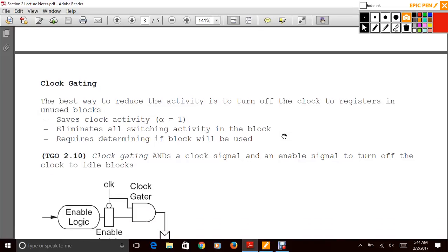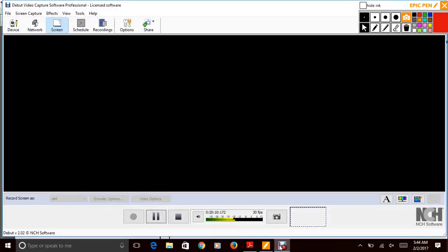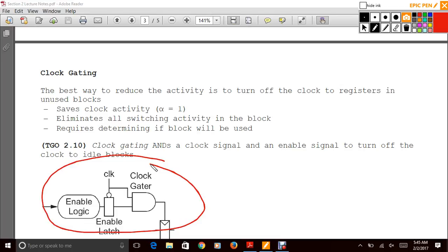So next, I want to go over some fundamental concepts on clock gating. How much time have we used? 20? Okay. Basically, there's a lot of ways to try to reduce power. The main idea is that we're going to focus on how to reduce power by turning certain portions of the circuit off or limiting the amount of power that's used, particularly in memory elements.